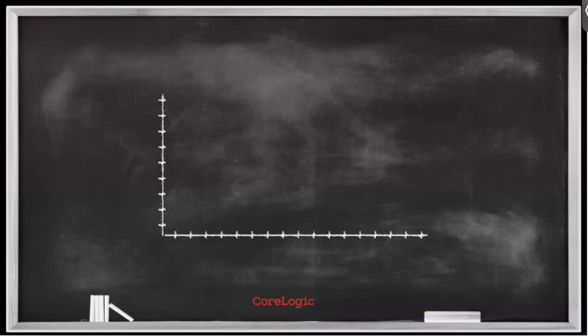The most common scale that we use in this industry is something called GPP, for that specific humidity or humidity ratio, which is the more technically accurate term. And this stands for grains per pound. Now, I'm not going to get real deep into psychrometrics today. We've had a number of sessions where we've dived down that hole real deeply. So I'm not going to get real deep into that.